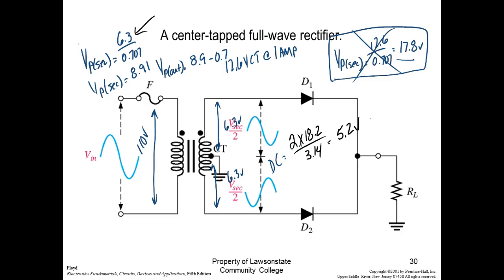When you put a capacitor in, we'll talk about capacitors later on, but what that is, is a filter, one of the main uses of capacitors. Now, we get capacitors where we don't want them. Anytime you bring two wires in close proximity, or if you bring a conductor close to ground and it's not shielded, you make a capacitor. But those are what we call stray capacitors or unwanted capacitors. But these guys have a function in life.